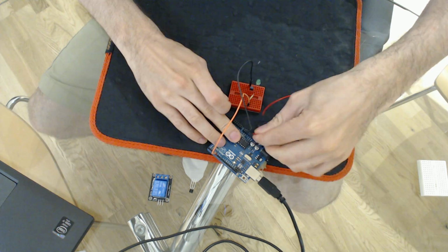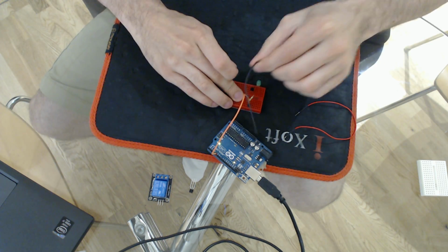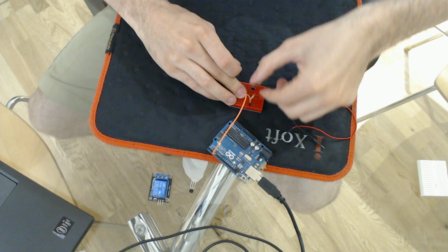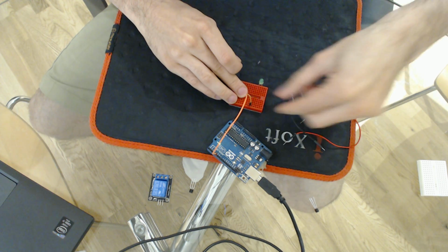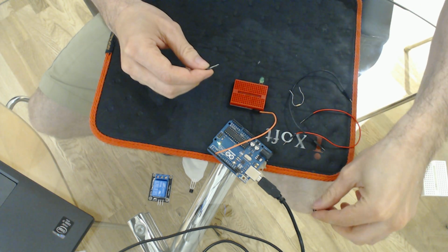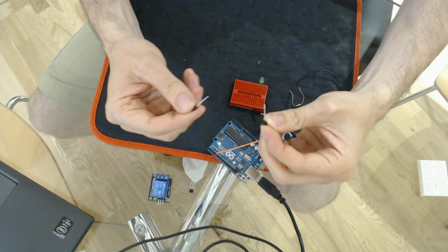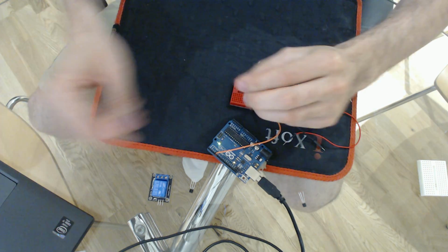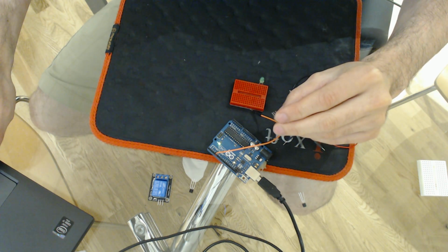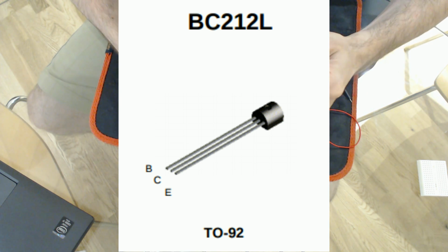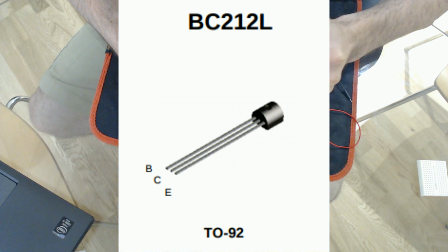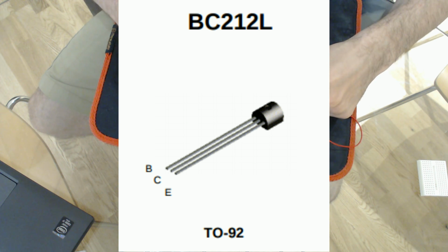So we can remove the cables here, all of them, just to make sure. So we just start from scratch. And then I've seen that between this version and this version, the pin order already changed. So if I go back to my datasheet and check which are the pins, the first one is base, collector and emitter.